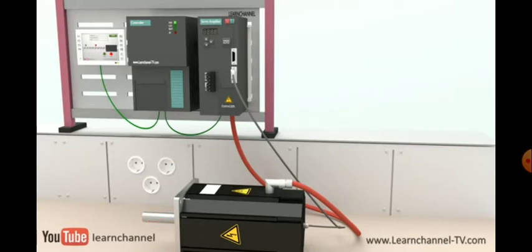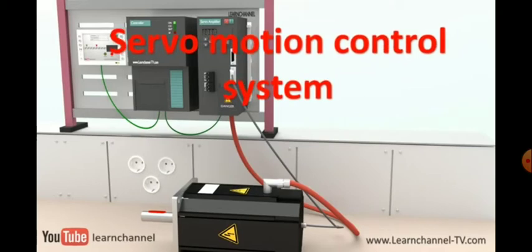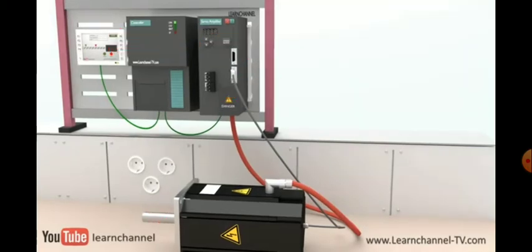But how do these devices work together? The servo controller sends low voltage control signals for position, speed, or torque to the servo amplifier. Now these commands are amplified up to high power, which the motor can use. The electrical pulses of a sensor are sent back to the amplifier. This amplifier uses this information to control speed and rotor position.